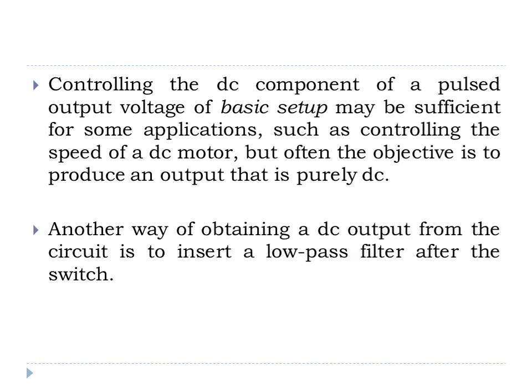In that case, we need to connect a low pass filter between the source and the load, so that the circuit is able to produce a nice DC output waveform. A low pass filter is designed using an inductor and a capacitor, which we will see next, and it is known as a standard buck converter circuit, and it will be analyzed in detail in the further section.